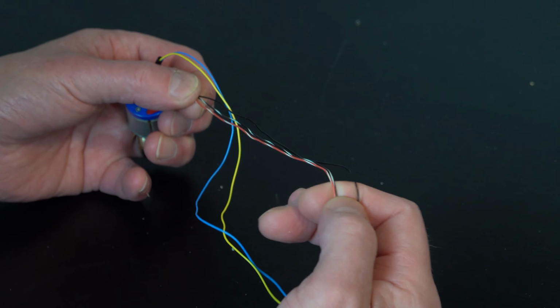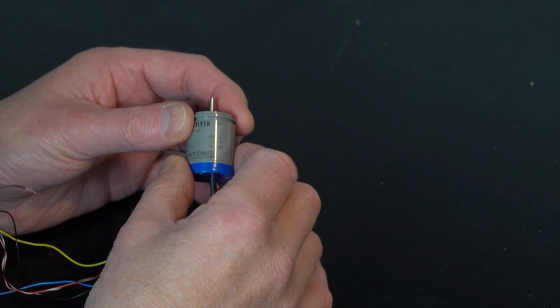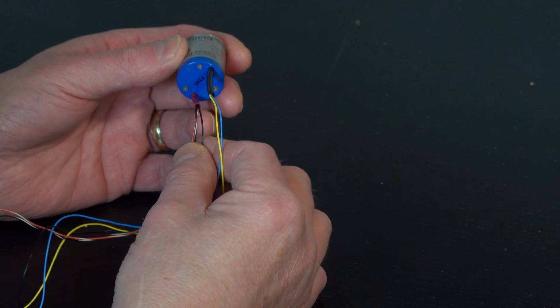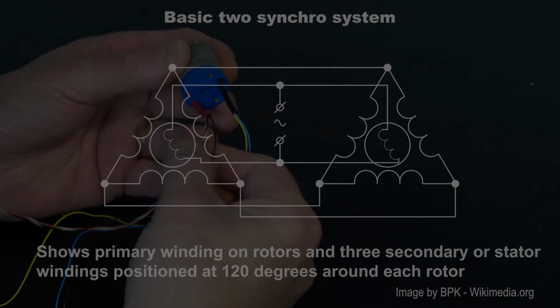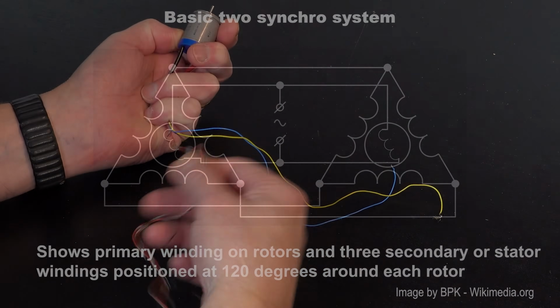Synchro units are transformers. Synchros typically have 5 cables, 2 for power and 3 to control the rotor position. In a synchro system, the transmitter windings and the receiver windings can be thought of as the primary and secondary windings of a transformer. The voltage induced in the receiver windings is proportional to the angle of rotation of the transmitter shaft, and the receiver rotates to the same angle as the transmitter as a result of the induced voltage.